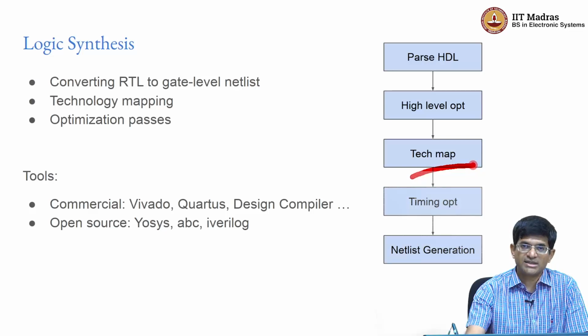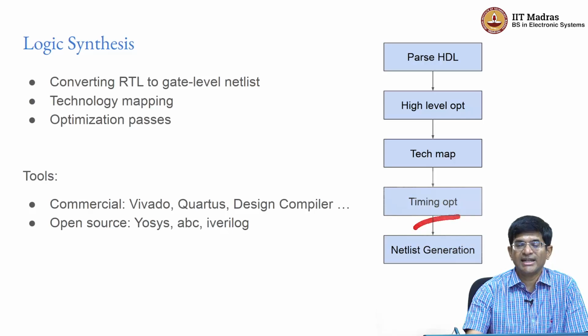If you have lookup tables inside an FPGA, then you have a bit more flexibility, but now should you be using 2 input lookup tables, 3 input, up to 6 input is probably allowed. So, how do you go about combining these different inputs in a way such that you get a good mapping of your equations into the hardware primitives that you have? Now, each and every one of those gates has a certain delay associated with it, which means that you can now start to perform timing analysis, which also means you can do timing optimization.